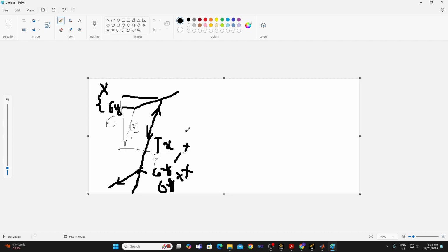Okay, typically a real material will have a combination of both isotropic and kinematic hardening, and the yielding in compression for this scenario would be somewhere between sigma y minus x and sigma y plus x. It is not purely isotropic or purely kinematic, but here we are going with purely kinematic hardening, because typically that is the more dominant effect, and this is also known as the Bauschinger effect. Okay, so if you want to know more about it, go to the internet and study about the Bauschinger effect. That is something a postgraduate student should know, studying the material behavior.